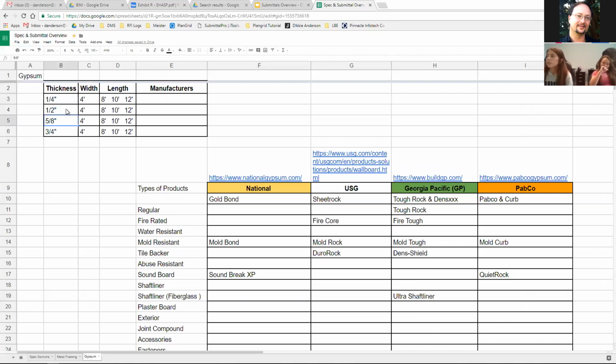Sometimes we need 1/2-inch drywall on ceilings or on certain walls that need to maintain a certain plane, meaning the wall needs to be furred out or built out so that it's a consistent line. They might use half-inch drywall to maintain a certain line on the wall.